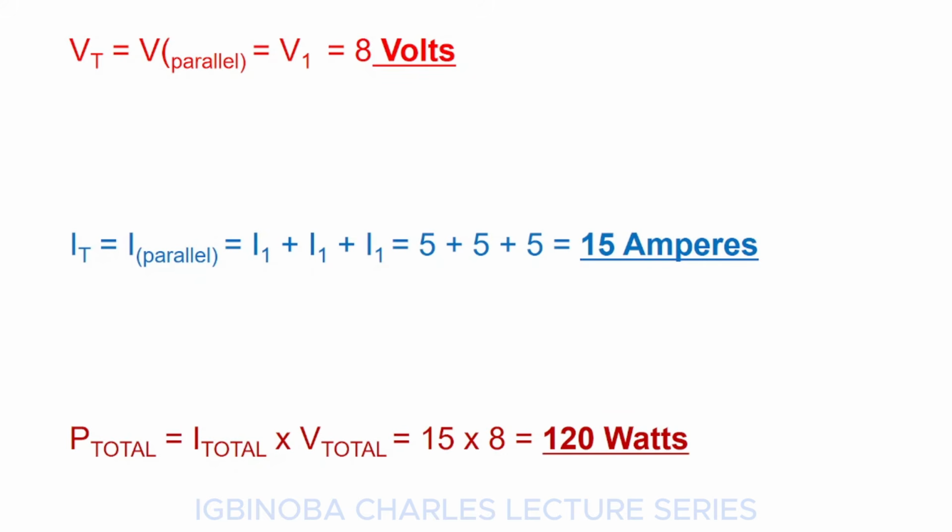However, at lower output voltage, this mismatch may not be a problem, but as the solar irradiance increases towards full sunlight, that is 1000 watts per square meter, the mismatch in the current voltage characteristics curve of each photovoltaic panel can cause a significant power loss in a large array.